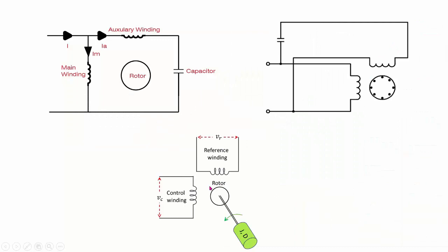And this will allow the rotor to have current flowing within it because of inductive effects. So the current in the rotor will be produced because of the flux inducing it, and this will again experience torque when the current within the rotor comes under the influence of the rotating magnetic field.